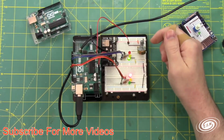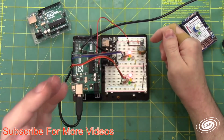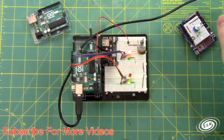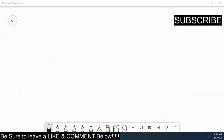I'm working on the most optimized code to do this, but in order to do this function, I need to use what is called a software interrupt to constantly read the value on this potentiometer so it can adjust the cycle in real time. And I'm going to show you what I'm talking about on the whiteboard. So we have the whiteboard here, and what am I talking about? So I have my setup and pin declarations is fine, but I have my loop here.